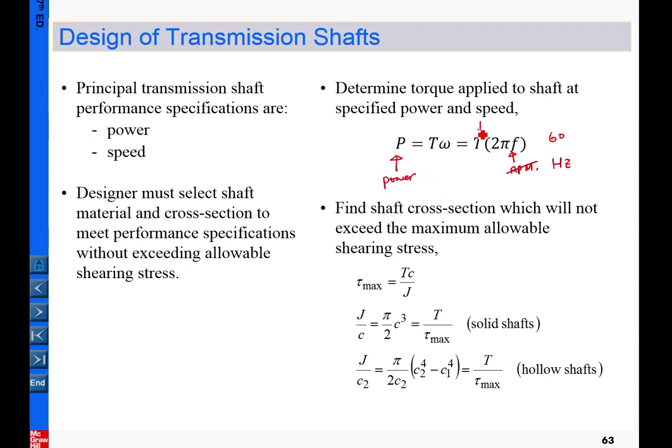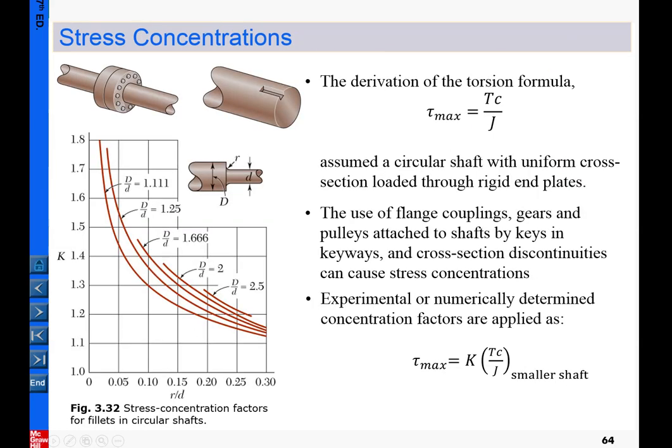T is the torque we've been studying in our shaft. For example, here this is our model. If this is the torque here, with material properties, geometry and dimensions, then we can calculate tau equal to TR over J, and the angle of twist phi equal to TL over GJ. So T is related to the formulas we've been applying. We keep this in mind, then we can see how much we can do.